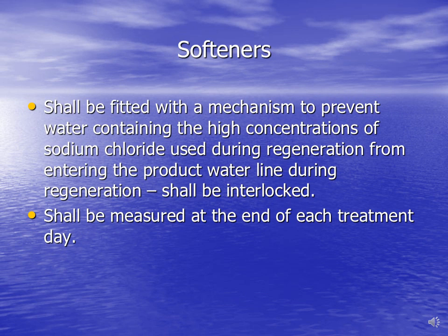And softeners shall be fitted with a mechanism to prevent water containing the high concentrations of sodium chloride used during regeneration from entering the product water line during regeneration, and it shall be interlocked. And it shall be measured at the end of each treatment day.